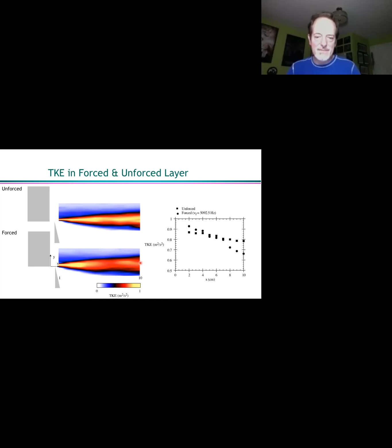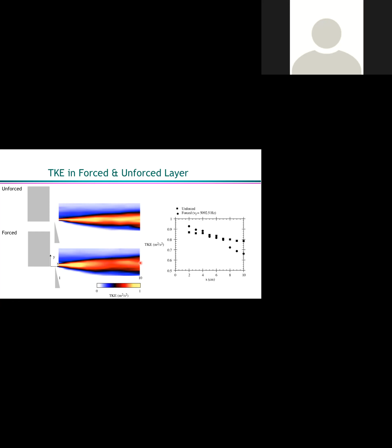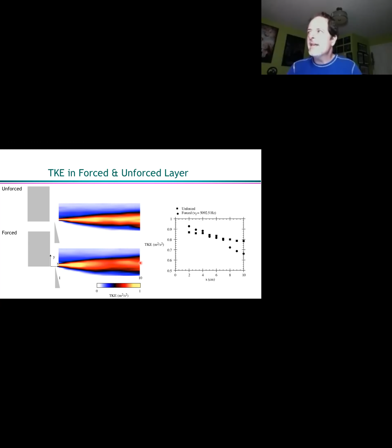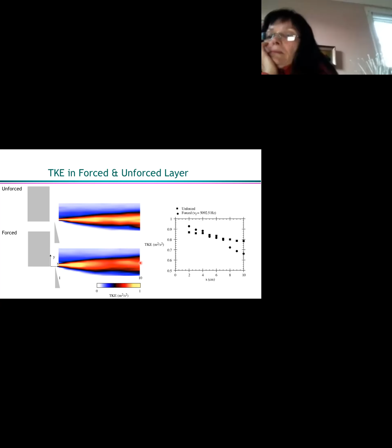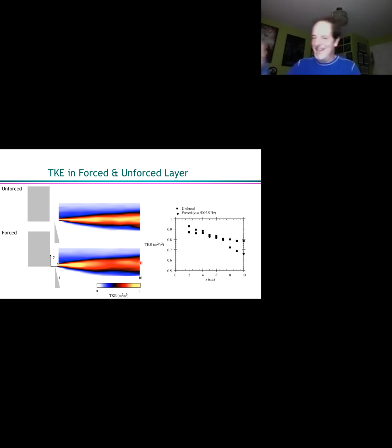So if you get to a much thicker, higher viscosity fluids, it'll still possibly work. Possibly. The downside though is just higher viscosity means lower Reynolds number, which means it's a lot harder to get something to transition to turbulence, right? You think of stirring up paint, you really got to reef it around. Whereas you pour some milk in your coffee, you just go boop, boop, and you're done, right?